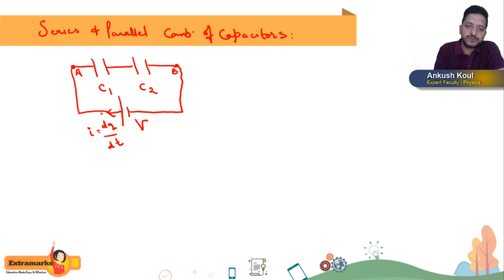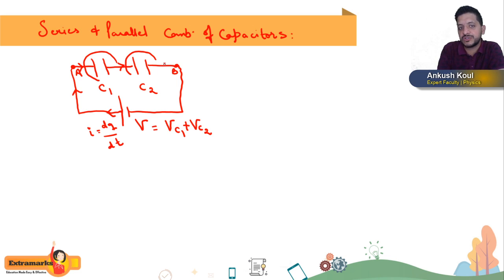So the charge starts flowing from the battery to the initially uncharged capacitors, and then this potential V gets distributed or divided among the two capacitors. So some potential goes to capacitor C1 and some potential is developed across capacitor C2. But if you look at these two capacitors, these two are connected in what, beta? Series. So whatever rate of flow of charge is in this line of the circuit, the same will remain in this line of the circuit, and so on.